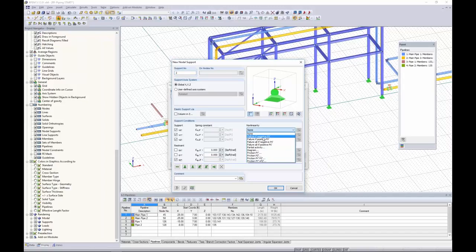I don't think it's completely uncommon that maybe for a piping support, you have some type of friction support. So it's dependent on your normal forces. You can define all that with the nonlinear capabilities within the program. I'll repeat this again, but the nonlinear supports is something that cannot be taken into account with result combination. So just keep that in our heads, but we'll revisit that later.